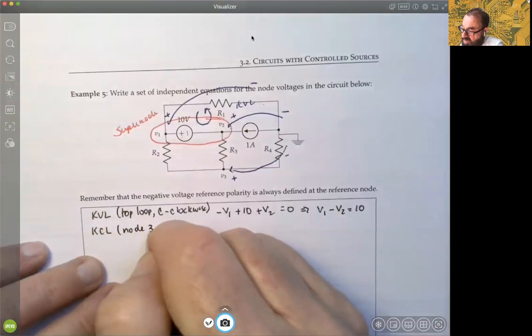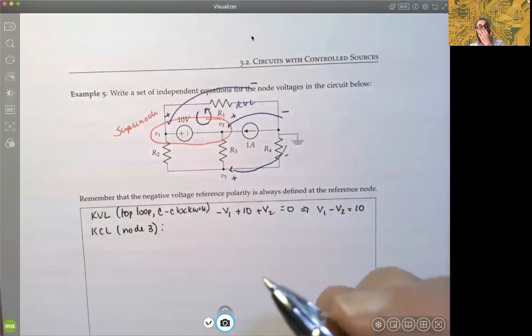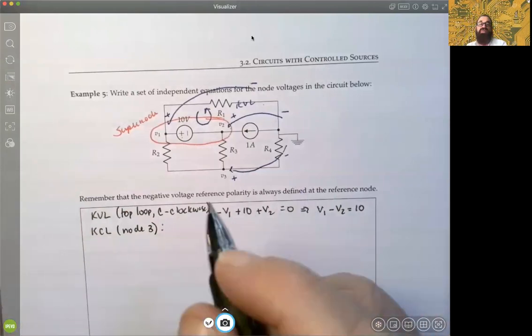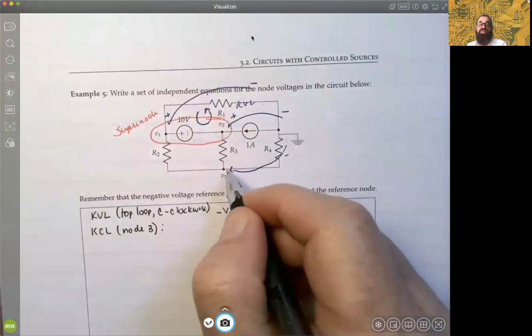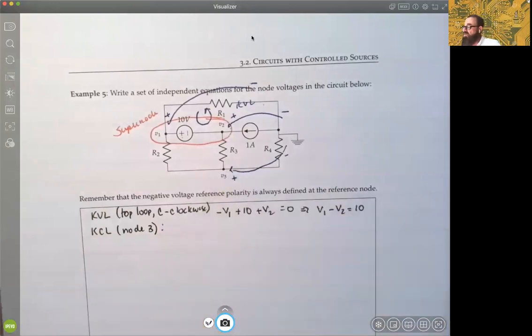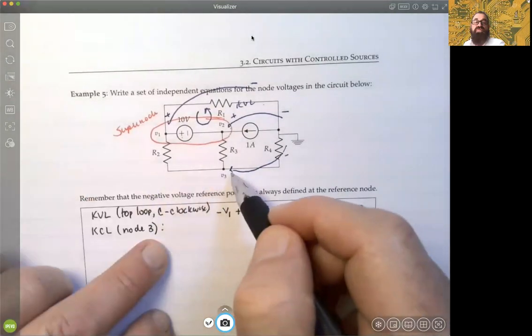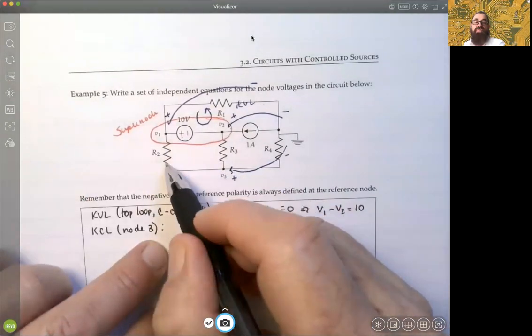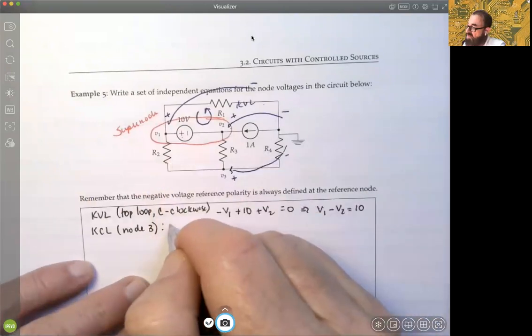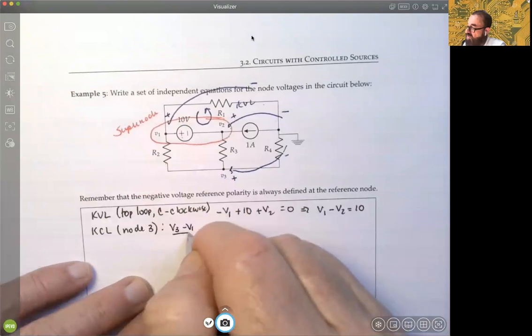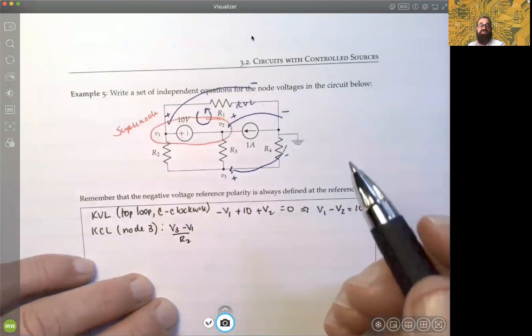Okay. Remember the approach of KCL is we're representing currents now, and we're representing all the currents coming out of this node V3 using our nodal voltage approach. Let's go this direction. We would go from whatever the voltage is there to V1 over R2, so that current must be V3 minus V1 over R2. Can do the same process.